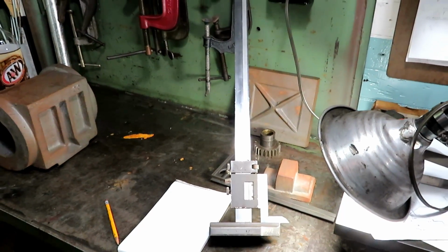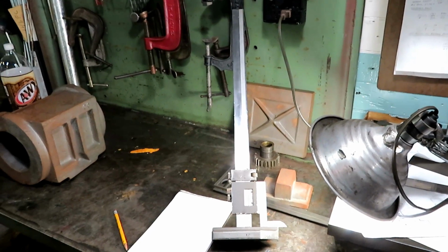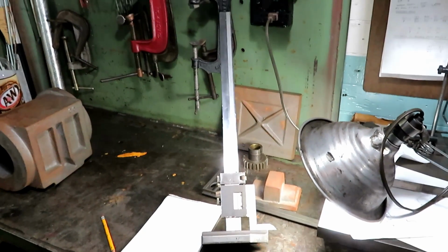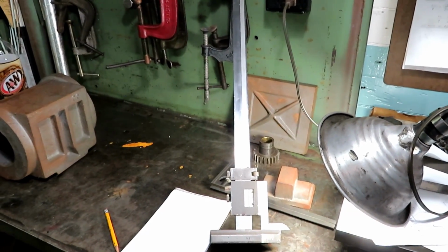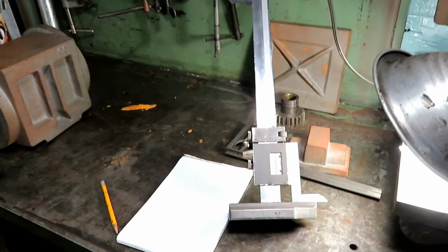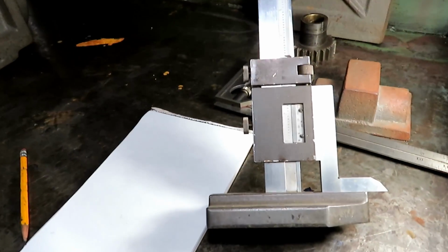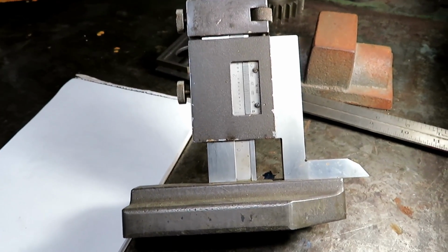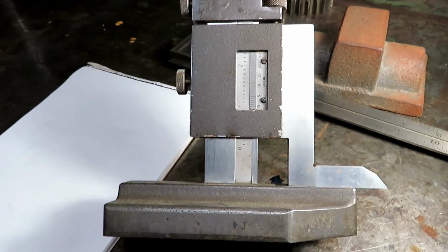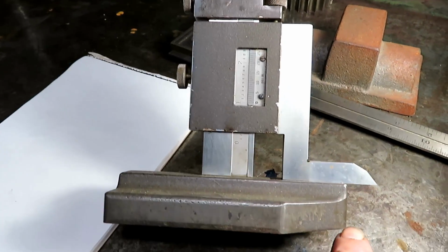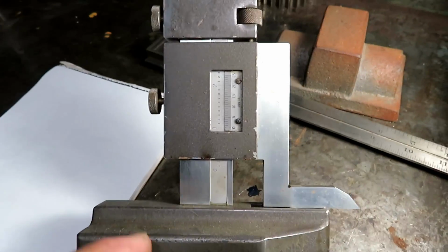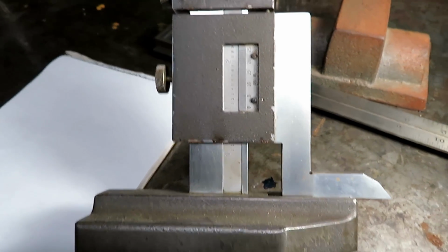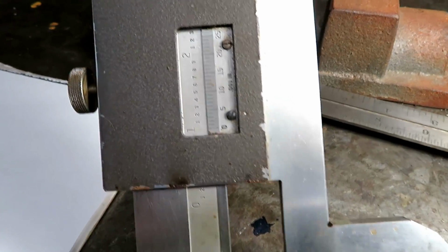I'm going to show you how to lay this out with an old height gauge. And I don't know how old this one is. Not an antique, but these height gauges have been around for a long time, and most all of the old ones worked with a vernier scale, and they were really very accurate. Now this is measuring the distance from the bottom up to this flat part of this point, and I want 1 inch 11 thousandths.